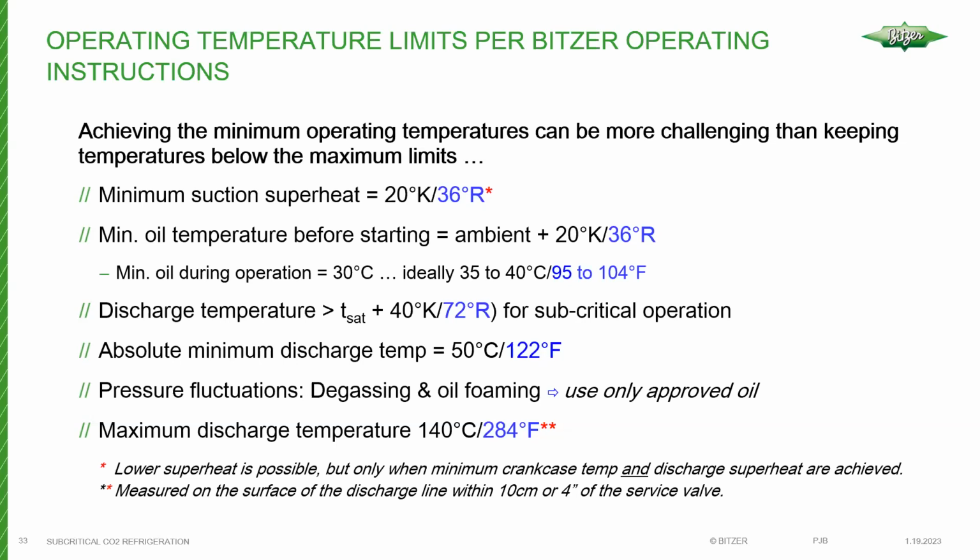And the longer it sits there without a crankcase heater on, especially with the higher pressures that we see in a medium temperature system, you're going to end up with more refrigerant in the oil. This is what becomes a problem. On startup, your oil has a viscosity that is just way too low. Probably somewhere down around 5 centistokes or something, when we're generally working with viscosities in the compressor that are much higher to lubricate the bearings. So every time this is done, it just reduces the life of the compressor.